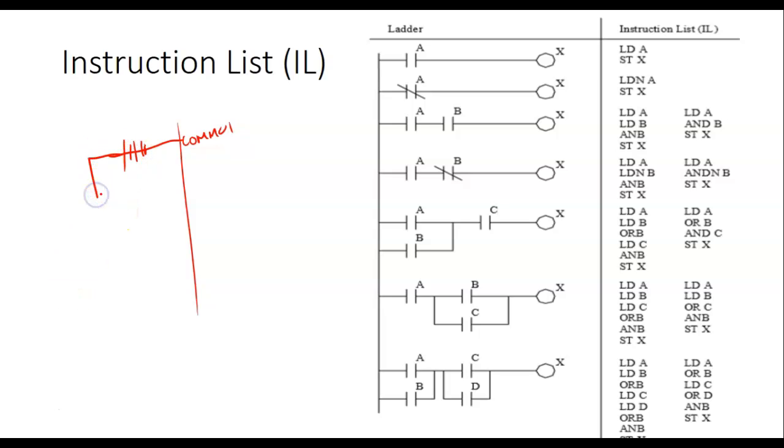And then I would come over here and put my input devices, and hook up each one of my input devices to one of my input pins. And they all wire the same. But in my PLC, let's just say these are inputs. These are push buttons, and this is input 1. And this is, let's say, 0, 1, 2, 3.